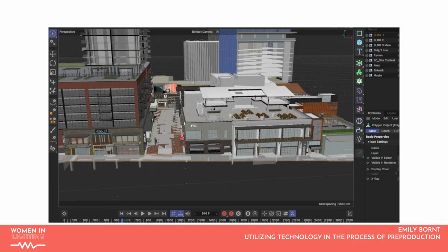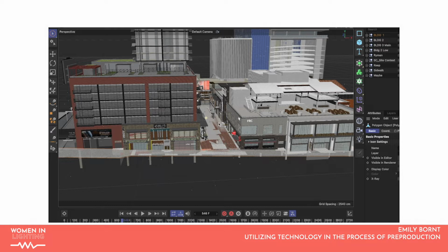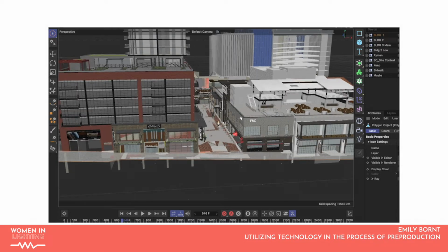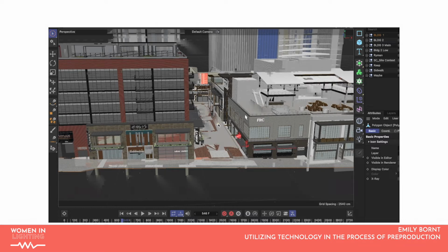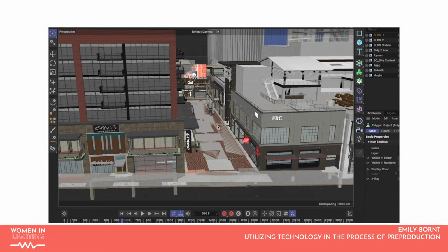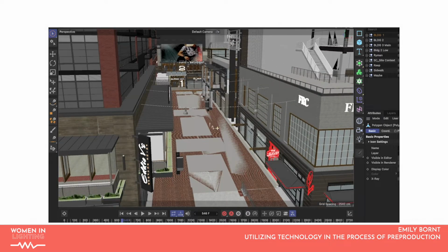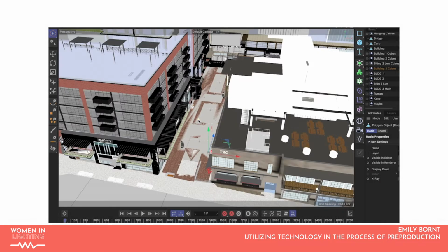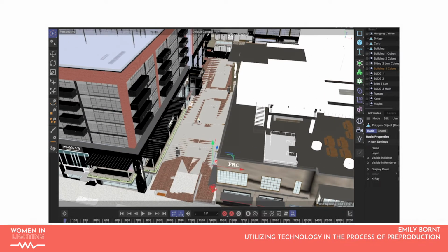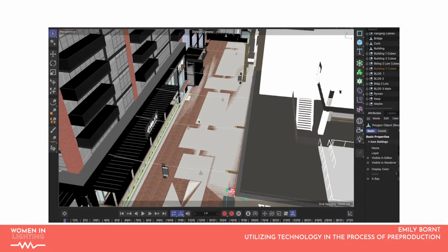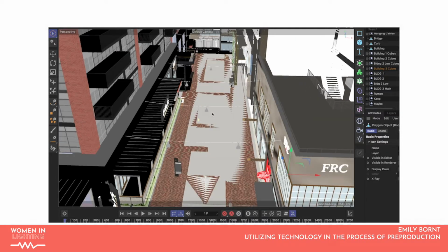For example, on the Nashville outdoor install I did last year, we received the architectural files as Revit files, which I was then able to import into Cinema 4D. It was an extremely large file, which slowed it down quite a bit. Moving around in 3D was slow and rendering was painful. I was able to use a search filter to find non-essential geometry and strip a large amount of unnecessary polygons out until we had the exterior framework of the buildings we were working on.